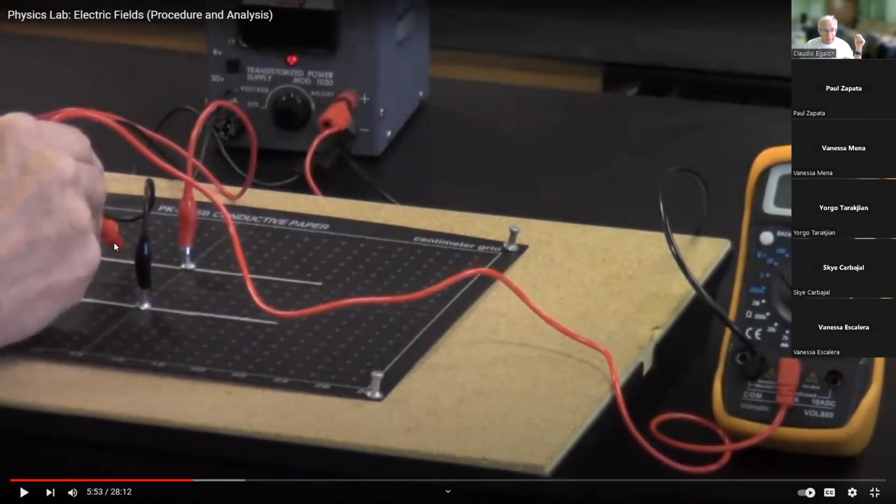See that? The probe, and let me see, where is this negative? Oh, this negative here. Okay, he was not careful about that. But this negative of the multimeter is also going to the negative of the power supply. That's your reference to make measurements. We can put it either here at the negative of the power supply, or at this other pin as well.